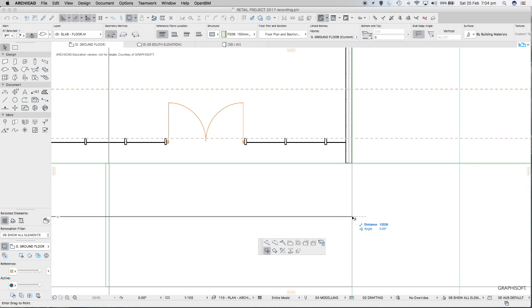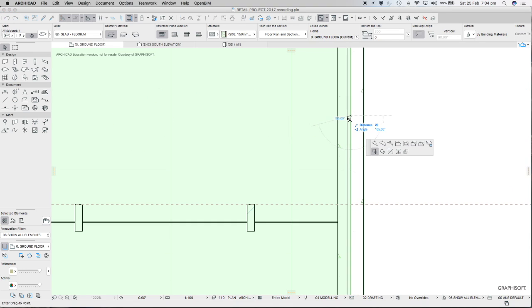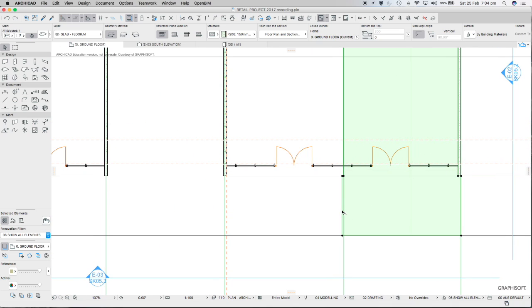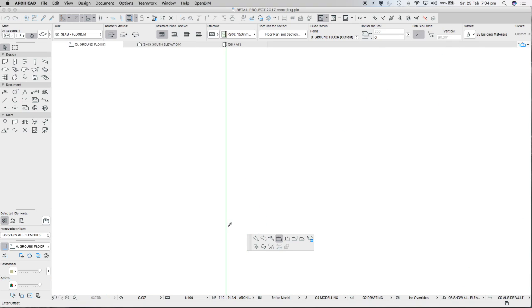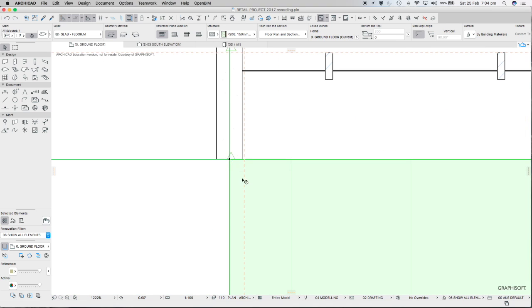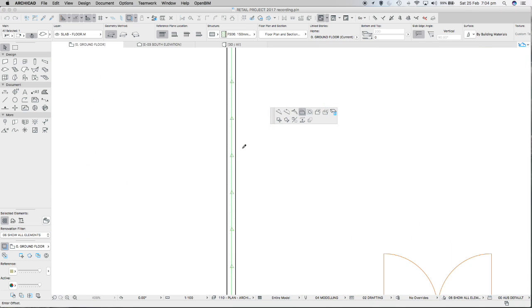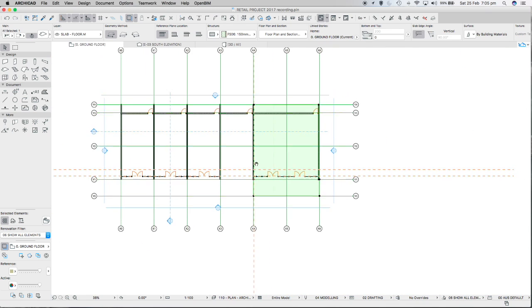concrete joints. So we need a copy of that, and then we need to do offset edge. So we need this one back on offset edge. So we can come back to there, and this one, offset edge will be set up, and that comes back to there. Doesn't seem to want to snap to it. I'm not sure why. If you come across here, you might pick up a midpoint through there. We want it done pretty accurately, and offset edge this one. Hopefully this one will snap to that edge line there. Yep, it does. Fine, set perpendicular.